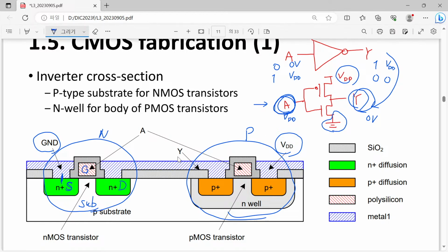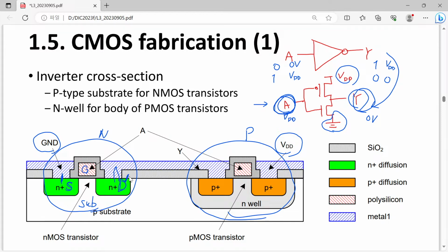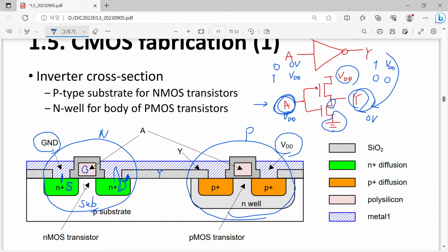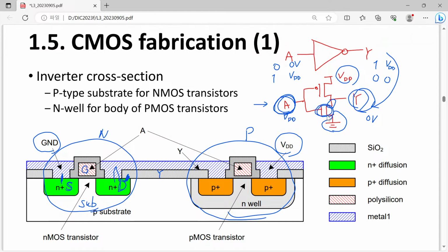That is shown here. The N MOSFET's drain is connected to this part, and this is output signal Y. You are now looking at the part shown here. Then in between, you have a MOS system, substrate and input A, and you can see that this vertical structure corresponds to this structure. So now you understand the N MOSFET is correctly wired like our schematic.